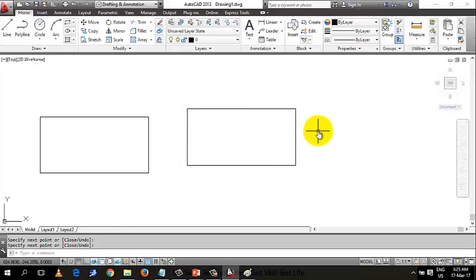You may wonder, why did we go through the trouble of relative coordinates? You will need relative coordinates in some instances as you advance in AutoCAD. But direct distance entry is a cool thing. It allows you to draw your lines straight away. So the dotted line must appear. If you don't enable polar tracking, let's try it again.